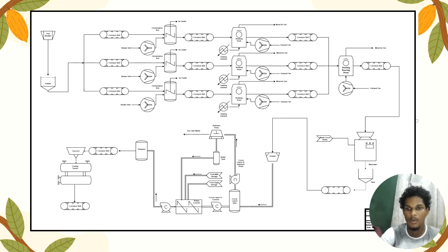The layout separates the wet and dry bean operations at the top from the liquid chocolate stages at the bottom, which improves hygiene, reduces cross-contamination, and simplifies ventilation and temperature control. We use parallel conveyors and duplicate fermentation and drying units to support well-ratioed production, ensuring that the factory can process batches with efficient use of machinery.